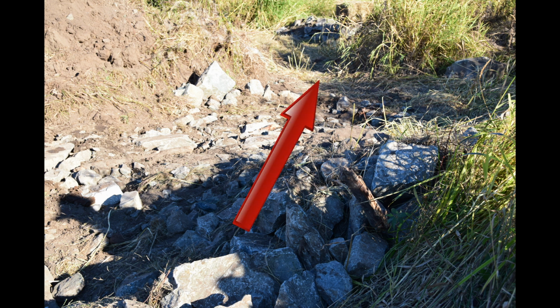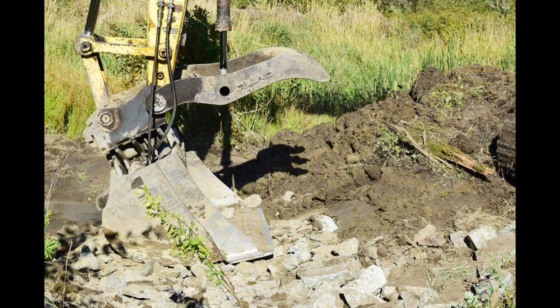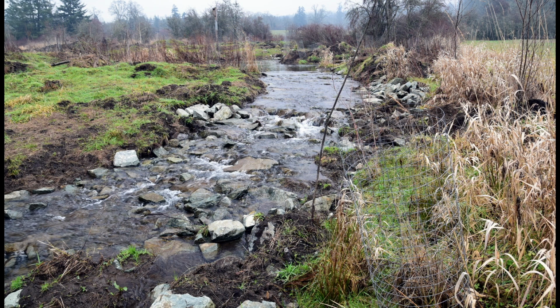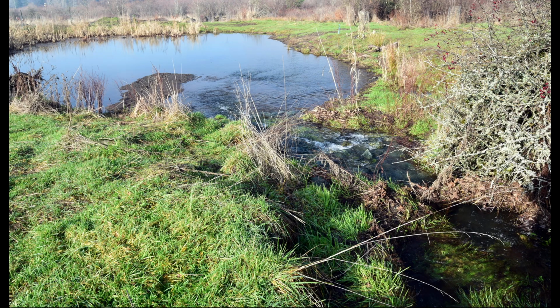The wetland spillways were widened, sloped, and armored with rock so they would not erode and form head cuts. The rocks used to armor the spillways were pushed into the ground using the bucket on the excavator. This photo shows one of the spillways with water flowing from the wetland into the ditch. Here water is flowing over a buried vertical grade control structure into the most upstream wetland we built.